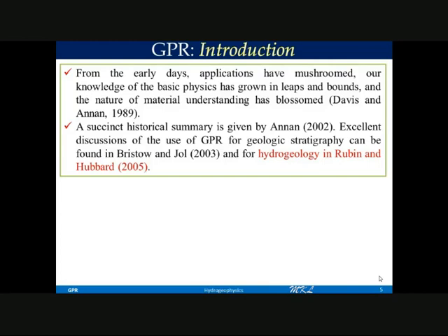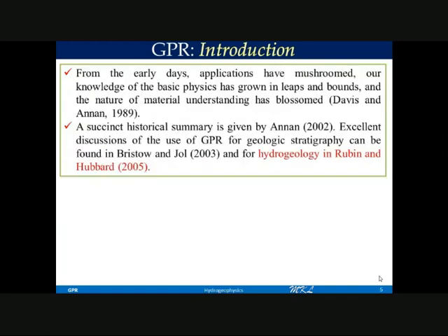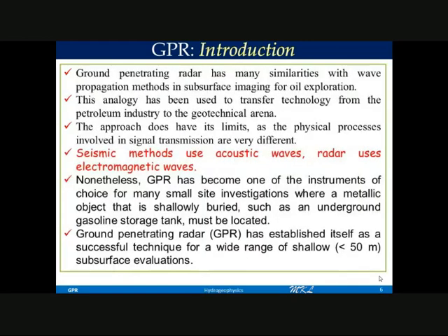There are other things, like Topp in 1980. He gave an idea of how the permittivity changes, and in moist or wet soil, what the relationship is between the moisture content theta and permittivity epsilon.